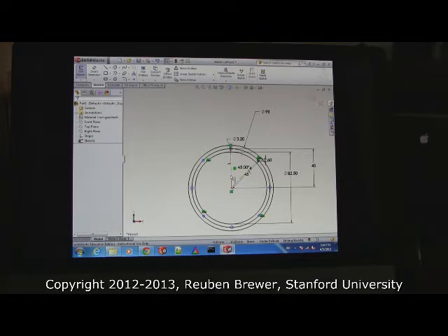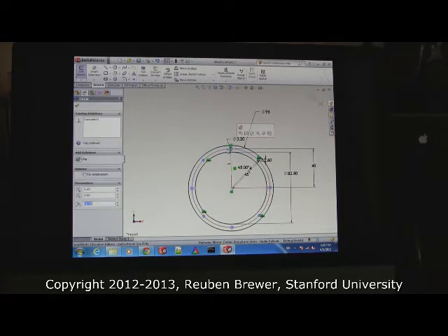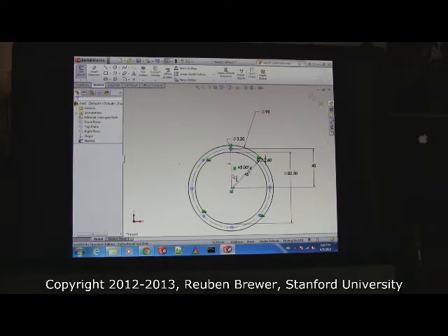It should be dashed. If we tried to build a part like this, it would get really confused, because it's like, wait a second, we have nested circles, but you can only have 2, right? It doesn't make physical sense. So, click that black circle, and on the left it tells you a bunch of different things you can do to it. You're going to click the for construction box, and now you'll see it turns checked. So now we're good. Okay?